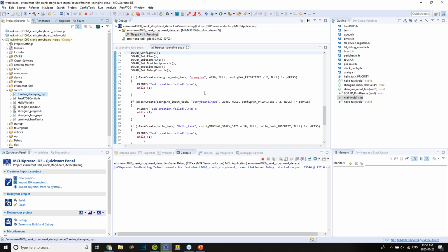But an event can be anything. An event could be the completion of an animation. It could be something that a timer fires and triggers a behavior, or it could be something completely custom that you define. In our thermostat example, you could have a set of events for temperature update, coming from an external source. This event could be injected into the UI with a data payload, and within Lua, or a C callback, you could grab that data payload and update the UI.